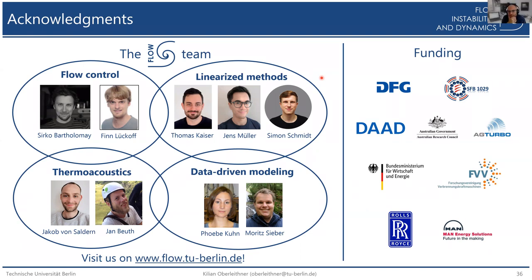We use intensified OH star cameras. Basically you use a normal camera or a high-speed camera, with an OH filter and then a light intensifier. Then you record your data, take a phase average of that data, and do a tomographic reconstruction of your heat release. Because you have line of sight information, you need to reconstruct the planar view of that heat release by assuming a symmetry of your phase average data, and then you get what you saw.